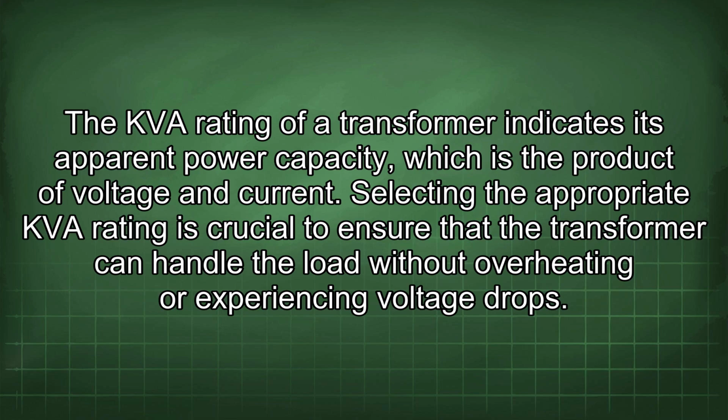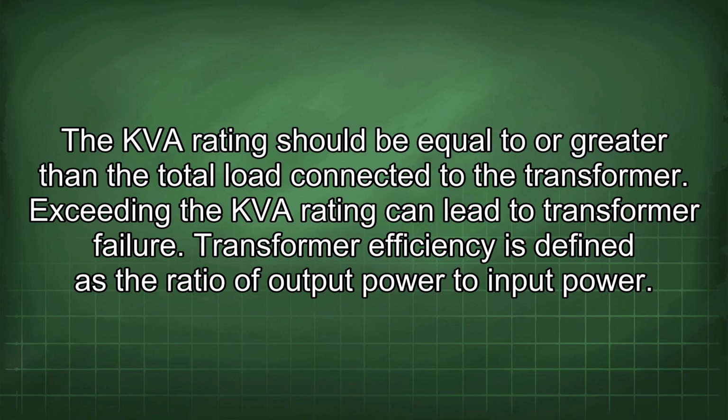The kVA rating of a transformer indicates its apparent power capacity, which is the product of voltage and current. Selecting the appropriate kVA rating is crucial to ensure that the transformer can handle the load without overheating or experiencing voltage drops. The kVA rating should be equal to or greater than the total load connected to the transformer. Exceeding the kVA rating can lead to transformer failure.